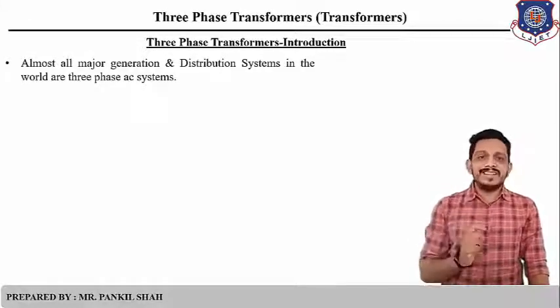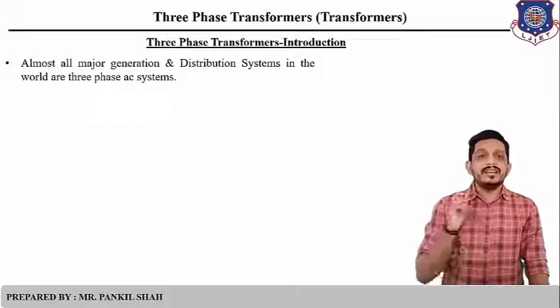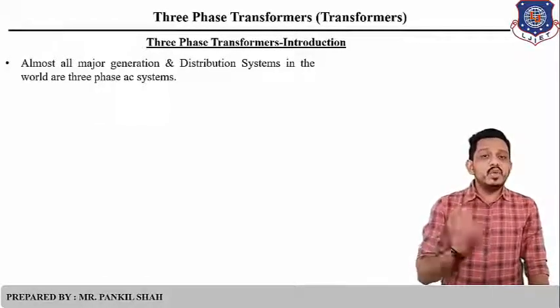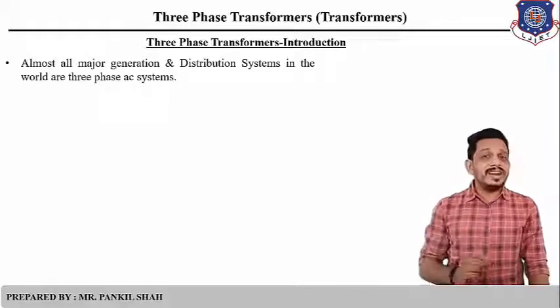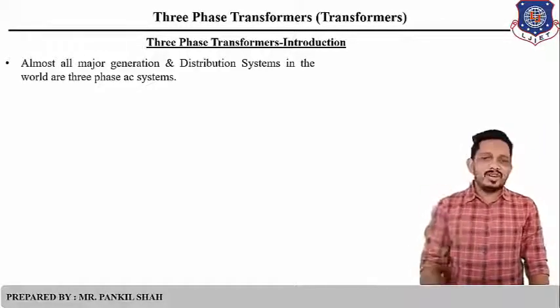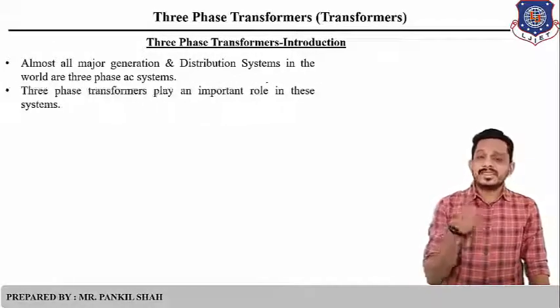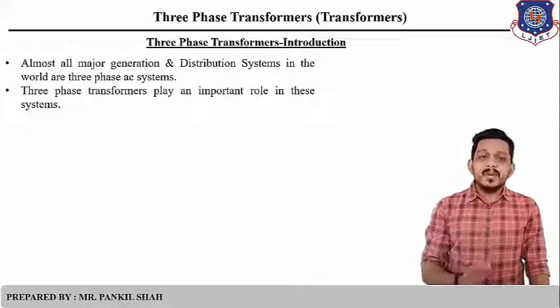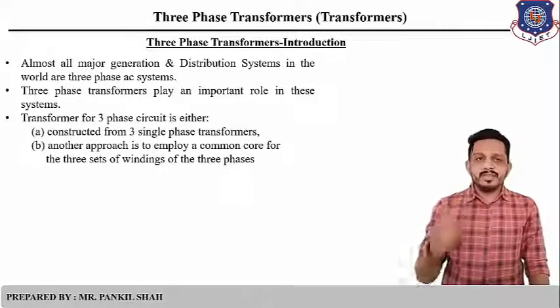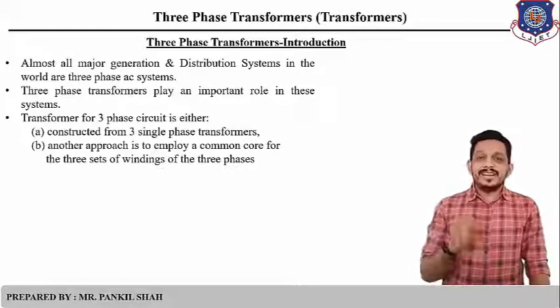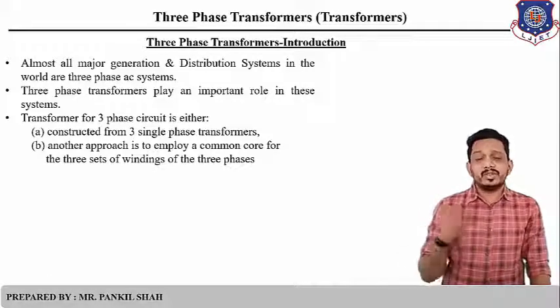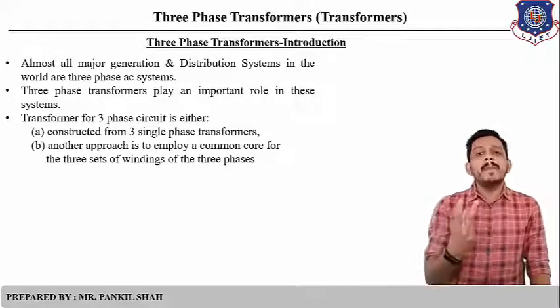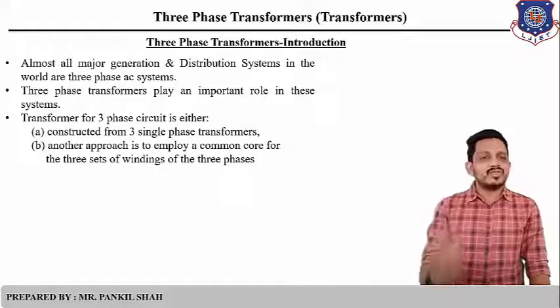If electricity is generated in three-phase manner, then the device that must be used to increase and decrease the voltage level without changing frequency is the three-phase transformer. So we are studying the three-phase transformer. Three-phase transformers play an important role in any type of system. For three-phase circuits, we have two methods to construct a three-phase transformer.